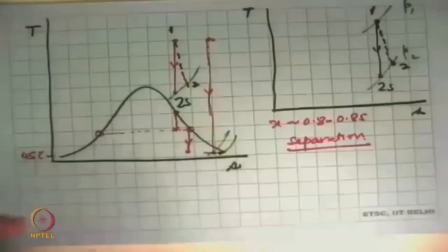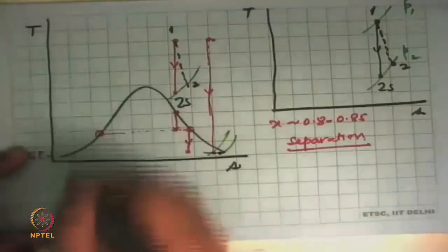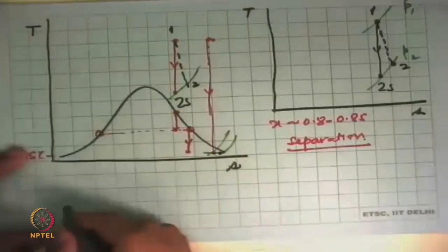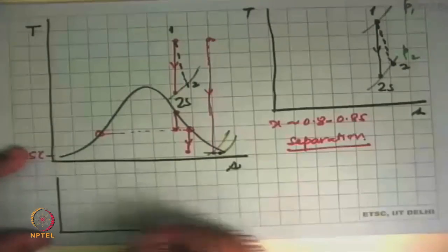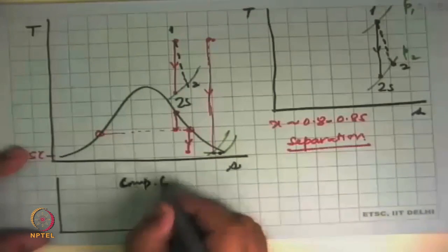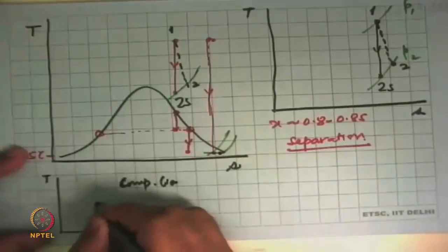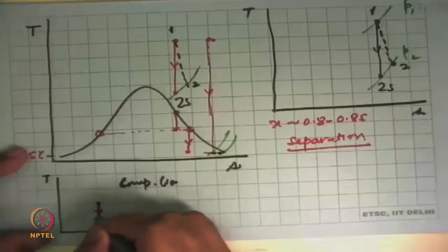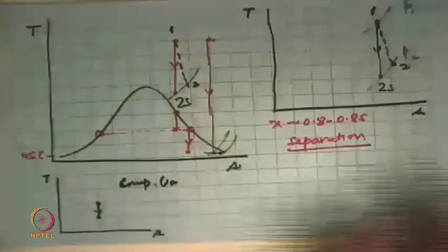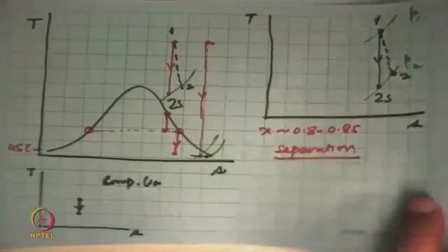Okay, so these are the type of turbines that are there. If it's a hydro turbine, well, on the same diagram, it will be completely on this side, but it will be too small. So if we blow it up and we say, forget about that, we are only looking at compressed liquid, S and T, then the hydro turbine will be like this. Okay, so that's how we show the processes for the steam turbine, all types of turbines.